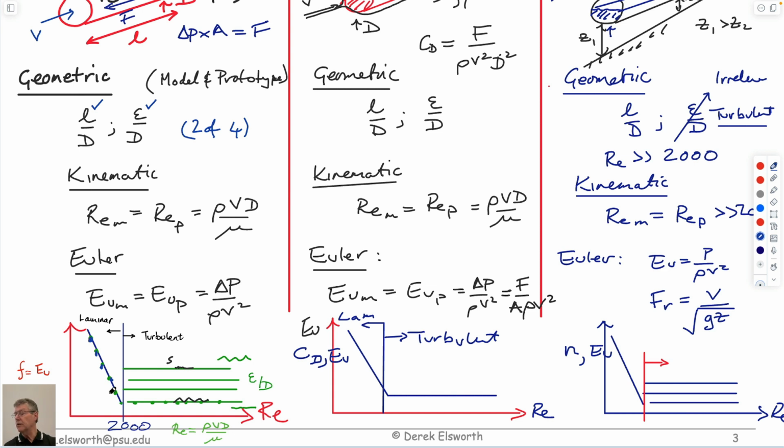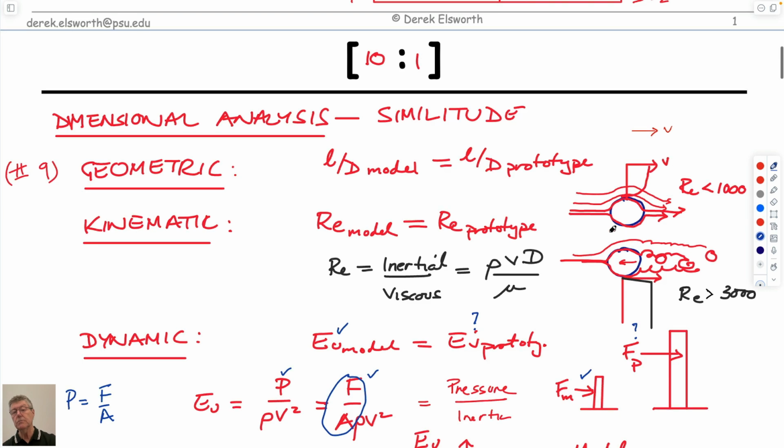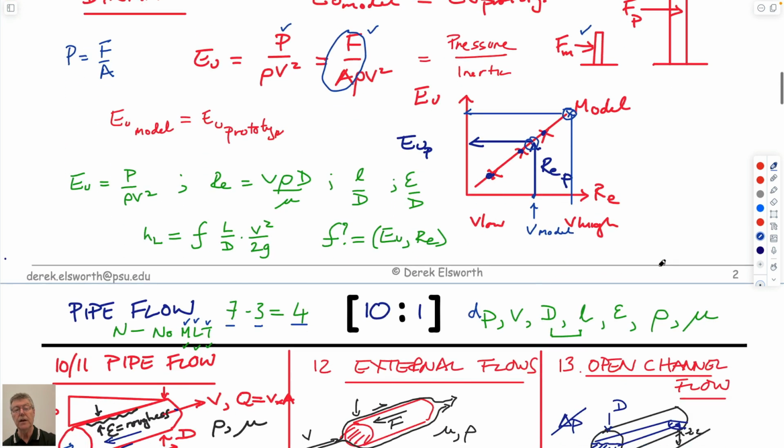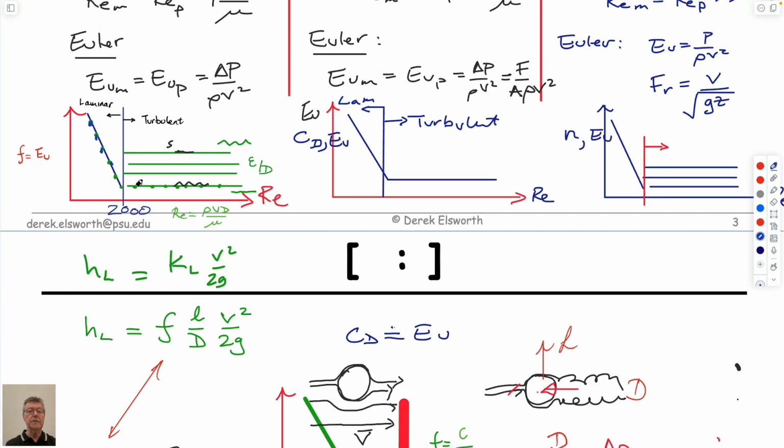So without knowing anything about your system, you can do a minimum number of experiments that give you a curve which characteristically is linear in the laminar regime. And then when you go above a Reynolds number of 2000, your flow switches from being creeping flow to having vortices in it. And you get a characteristically different flow. And so if you did the experiments at increasingly larger Reynolds numbers when it's turbulent, you get some points that go along here. And so that would define a fundamentally different curve.